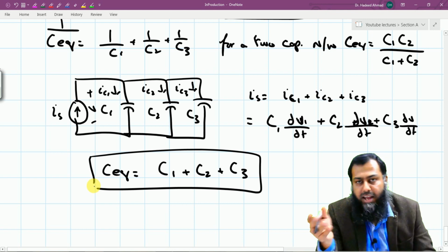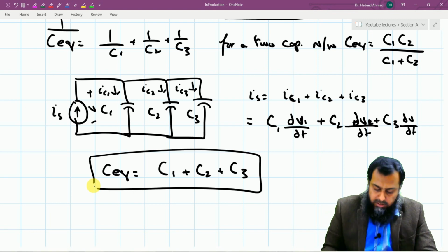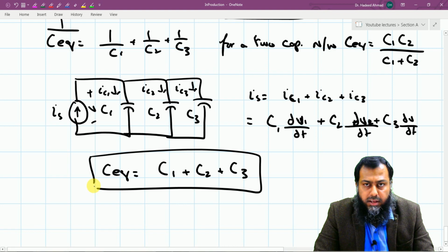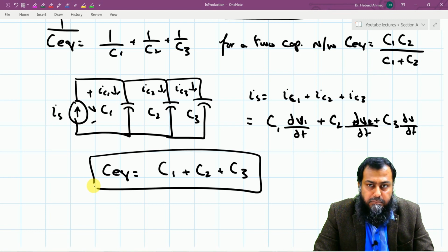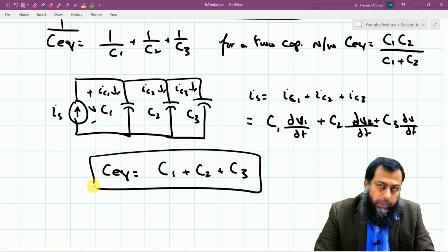Notice here that we have a different situation for the capacitor, because the capacitor is adding in a similar way like we added the resistances connected in series. But this is really a very interesting phenomenon, because for most of the time, if some capacitance of higher value is required, because the size of the capacitance also matters a lot, it is sometimes recommended to have two 500 microfarad capacitances in parallel to obtain a 1000 microfarad capacitance, provided that the voltage rating is fulfilled. That actually reduces the financial burden which is associated with the capacitors as well.